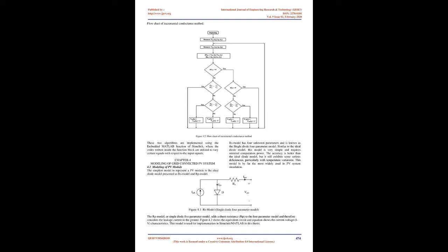This point on our example curve is where the voltage is 17 volts and the current is 2.5 amps. Therefore the maximum power in watts is 17 volts times 2.5 amps, equaling 42.5 watts. The power, expressed in watts, at the maximum power point is described as peak, maximum, or ideal, among other terms. Maximum power is generally abbreviated as PMP. Various manufacturers call it maximum output power, output, peak power, rated power, or other terms.